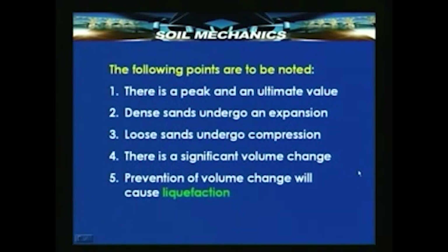We can summarize our observations like this. There is a peak and an ultimate value when a sand is subjected to either direct shear or triaxial shear. Dense sands undergo an expansion, loose sands undergo compression. There is a significant volume change in both cases.